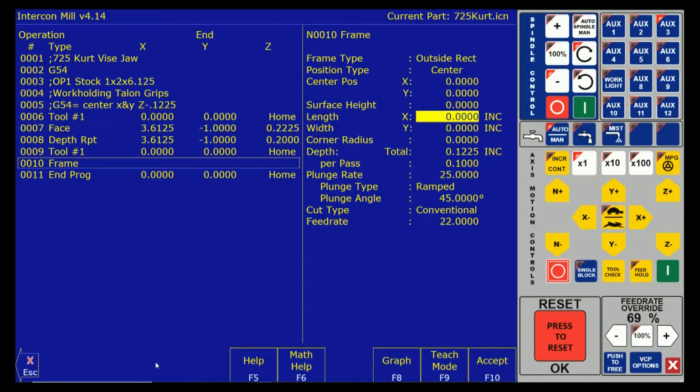Now, we mentioned a minute ago that our machining decisions are to rough and then finish, and we need to leave roughing material behind. The question is, how much roughing material do we want to leave behind? One difference between our rough and finish of the profile is that we're going to be making depth cuts with our rough tool, but our finish tool is going to be full depth, so 0.745 of axial engagement on that cutter.